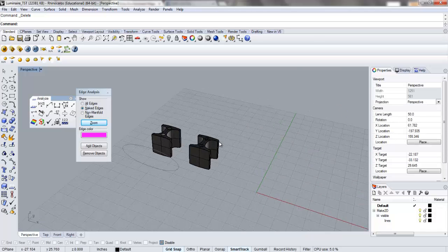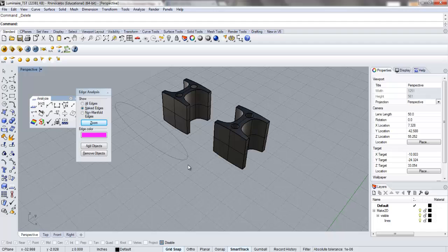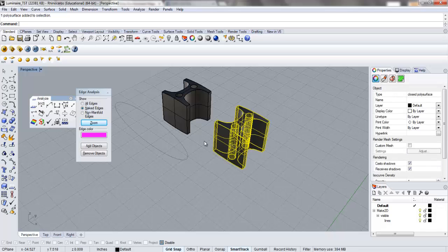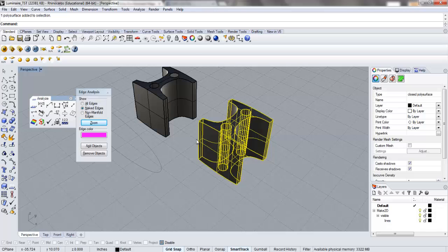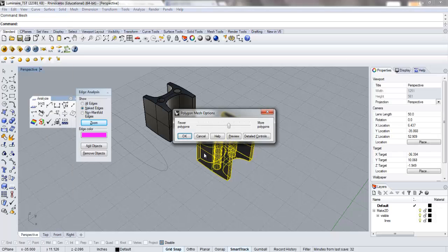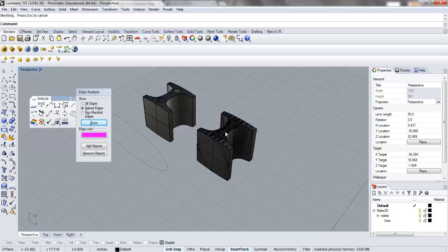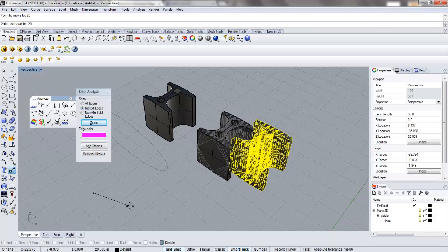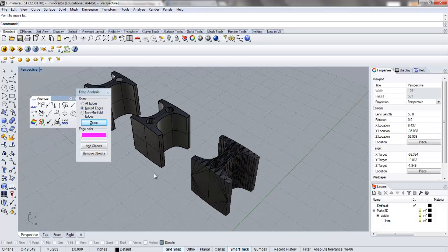All right. From this point, what we're going to need to do is mesh this first, because this is not in a condition that is going to be recognized by the 3D printer. The file format for that is STL, or stereolithography. So we'll go ahead and type mesh to turn that into a mesh. And you'll note that this is a little bit of review. At this point we can toggle through the number of polygons. So we can select now our mesh, and I'm going to go ahead and move that away, same distance, so we keep everything at even spacing.